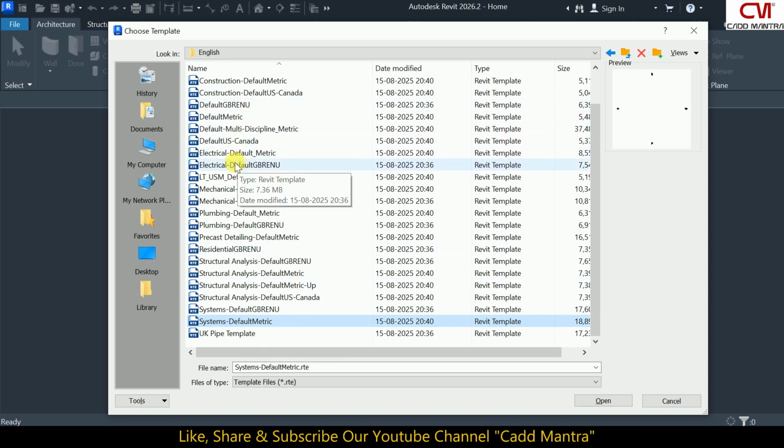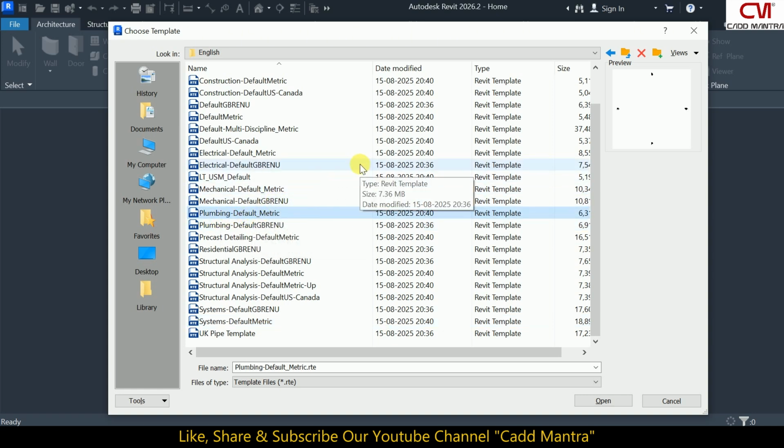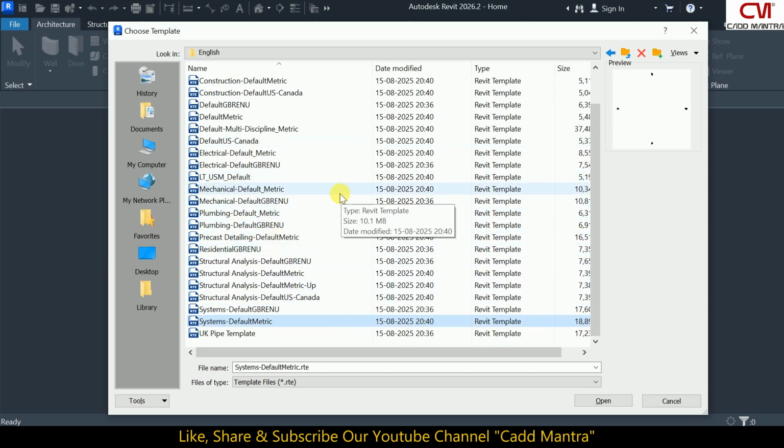If you select the electrical template, the mechanical parts will not work in that, and so on. If you are choosing the plumbing template, only the plumbing parts of the software will be active and work properly in this template. So if we want plumbing, electrical and mechanical, all three aspects of the software to work together, we will have to select systems default metric. So this is the file that we are looking for, systems default metric. Be sure to select the right template, because if you select the wrong template, this will cause a lot of problems when you open the file.